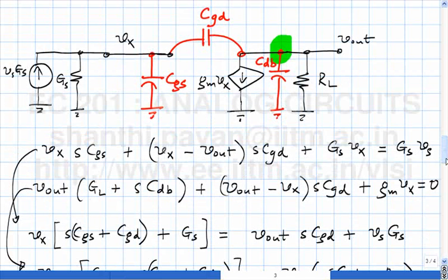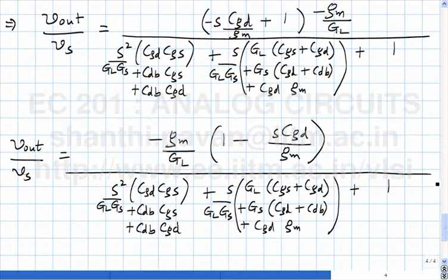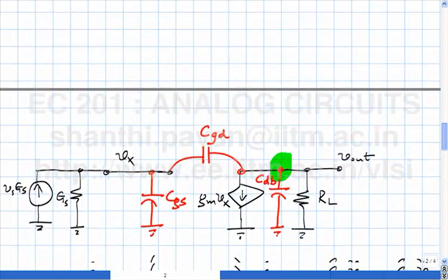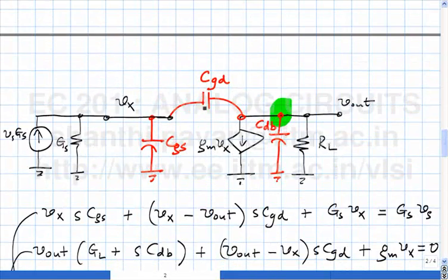Stare at this network and tell me why the order is 2. One reason, of course, is we assume that the math is correct and then we get 2, so its order is 2. The number of state variables is 2 because you can't independently assign states to CGD, CGS and CDB. Once you know the voltage across CGS and CDB, the voltage across CGD is automatically fixed.